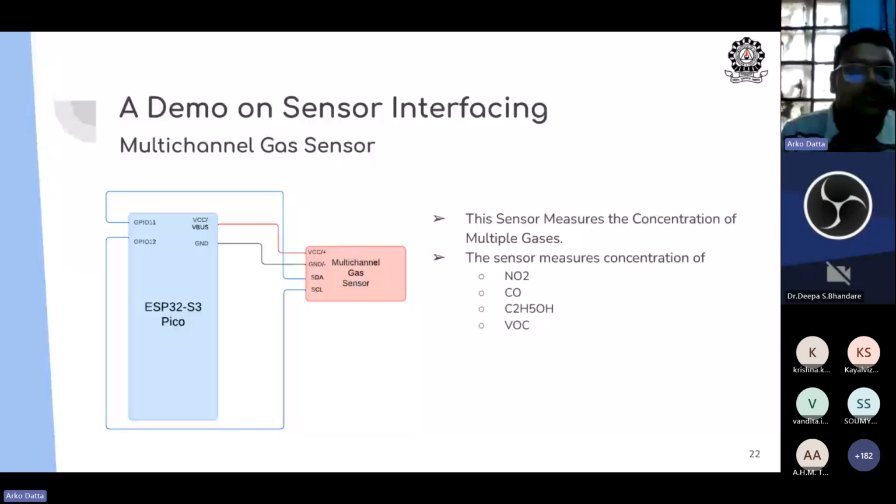So that address is provided to the microcontroller, and now the microcontroller knows that okay, if I go to this place, we will get some gas data. Apart from that, we are reading the bit stream as usual, and we are collecting the data of the gases. Where can I get that address? The addresses are provided in the data sheet.